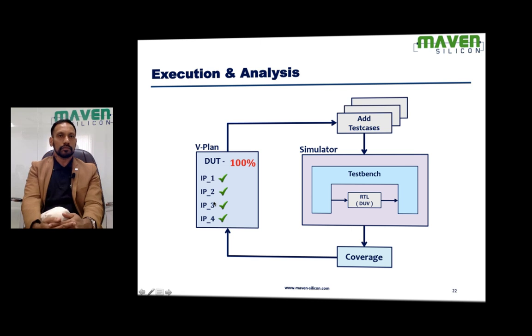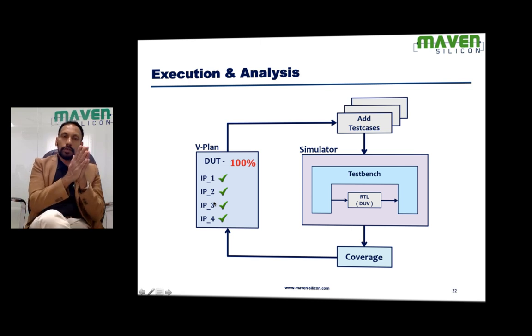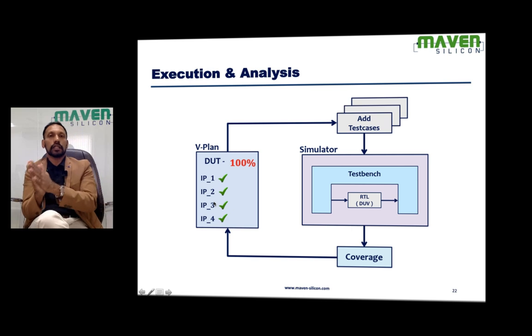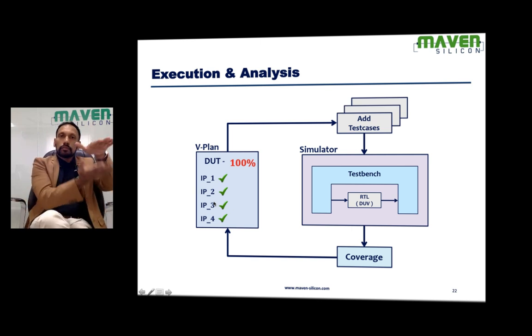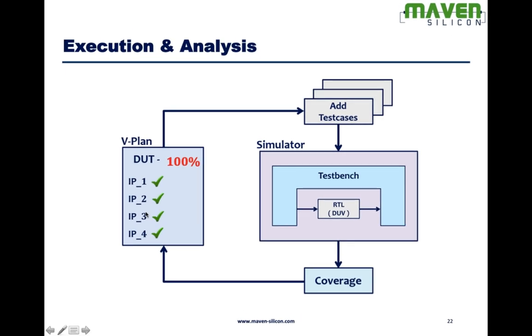So there is a huge difference between verification plan and test plan, they are not the same. When it comes to test plan, we think everything in terms of test cases, and for every design feature we write a test case. But when it comes to verification plan, we think everything in terms of DUT features and coverage. All right.